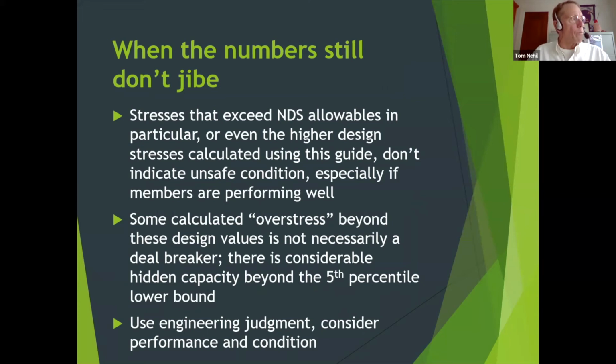One thing I like to make at least the consultants consider too is that even if on paper, after all this, you're still seeing a little overstress on paper, it doesn't mean that you have an unsafe condition. If you are seeing good performance and you have a history of use in this building, what's happening is you've got sticks that have been load tested. And so you have to think back to that 5th percentile lower bound. The sticks in the building may be telling you that that 5th percentile was an overly conservative assumption for the material in this building.